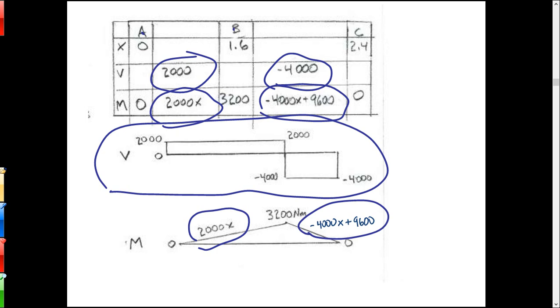Okay. Often the governing factor on designing a beam is moment. Shear comes in sometimes, but on the longer beams especially, it's moment. So when you look at that diagram, notice what happens at the ends. The moment kind of tails off to 0.